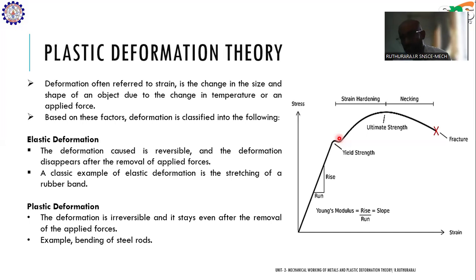Only ductile materials can be used in load-bearing applications because even after elastic deformation, there will be plastic deformation, and after plastic deformation, you will have a process called necking. Necking is the formation of a smaller part, and then fracture happens. So it is a time-consuming process, and it is a clearly visible process. Whereas if you take a brittle material, it is a sudden process. That's why for load-bearing applications, you use ductile material.